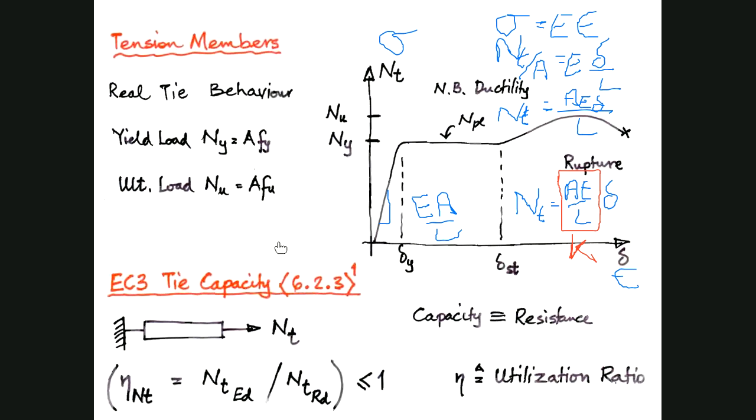And then at the connection, say if we have holes in there, we're allowed to have some more brittle failure, we're allowed to push a little bit harder there. So therefore the ultimate strength, we're going to go to this part of the curve up here. The ultimate strength is the net cross-section area down here, times the ultimate strength. We're going to multiply by 0.9 to reduce it down because of the uncertainty associated with the ultimate up here, and divide that by gamma M2, and gamma M2 is 1.25 because of the non-ductile nature of the type of failure in there.